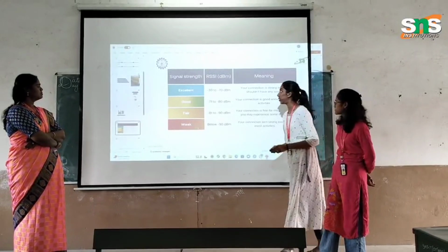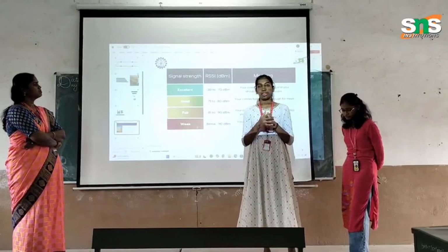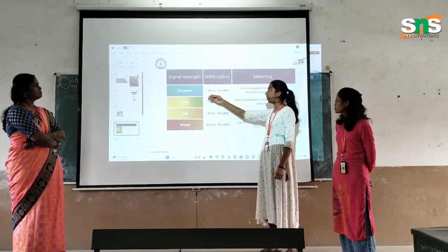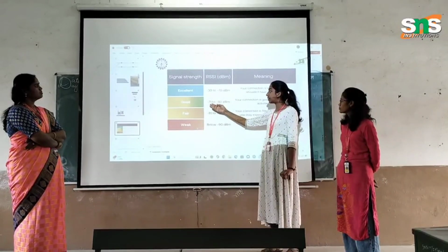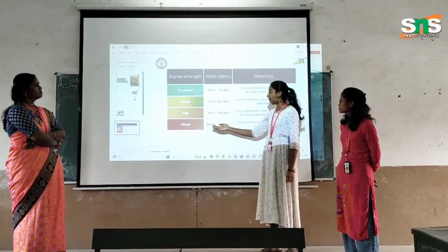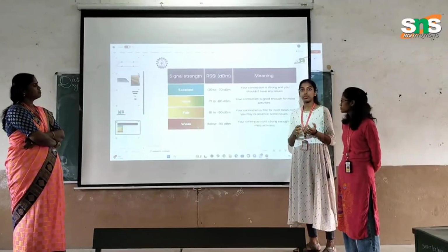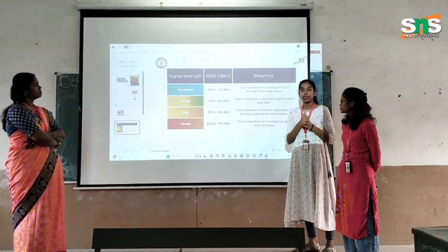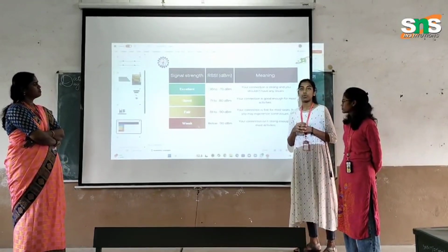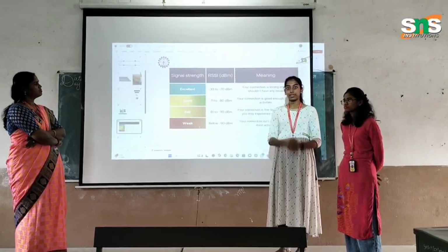Next is signal strength. We have done a mini project on a signal strength detector. When the signal is around -30 to -70 dBm, it shows excellent, and when the signal is around -71 to -80 dBm, it shows good. -81 to -90 means it's fair, and below -90 means it's weak. The signal strength will be detected through the ESP32 chip, and we have done the project using Arduino IDE. It is free software used to control sensors and actuators.